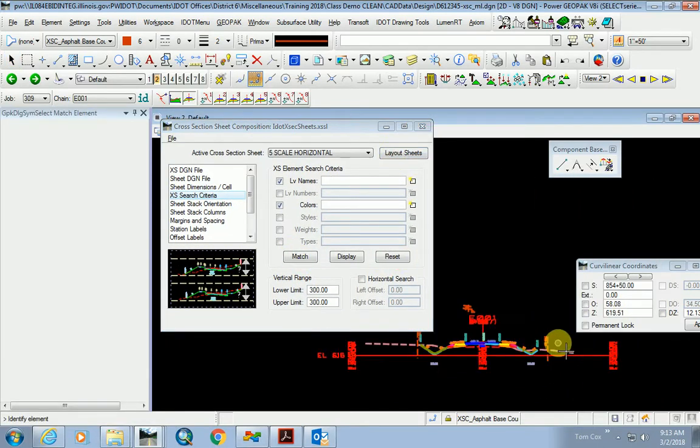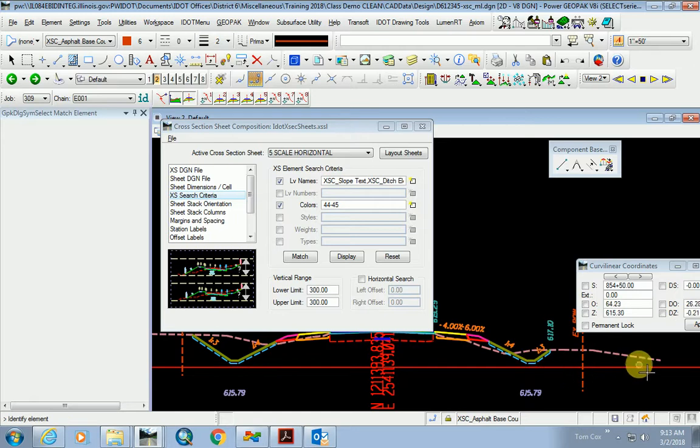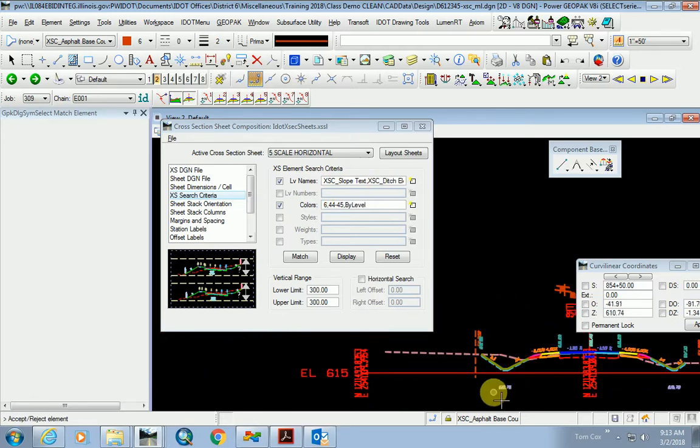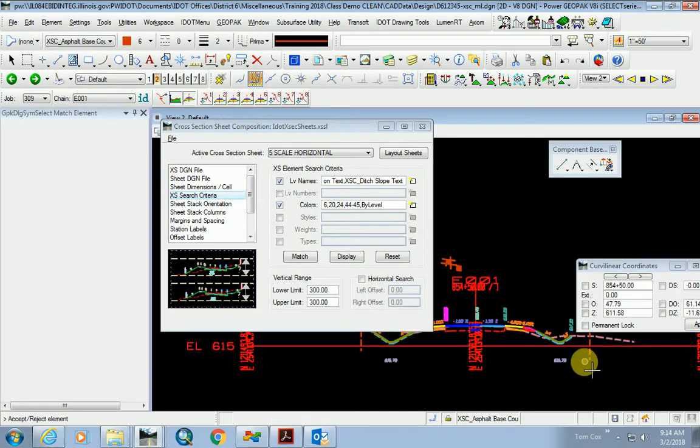And I just want to make sure that I'm picking up on levels that are as far out as possible, because it's going to go to the outermost one. And as I am hitting a match here, see, it's grabbing all those levels, so I should be good now. And so then when it clips the reference, it'll go at least to that bottom text and then up here.